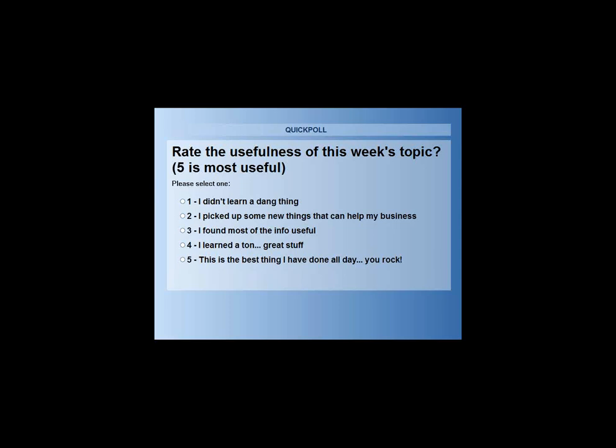Cliff asks, why use SAV rather than VAV? Does it cost less? Really, it has nothing to do with cost. It has to do with control. A VAV unit, to change its airflow, has to look at a pressure sensor in the duct. If nothing is changing in your duct system to change the pressure, the VAV unit will never slow down. So a VAV system only works if you have VAV zone dampers out in the duct. If you don't, nothing changes the pressure, hence it doesn't see anything, hence the VFD never slows down.